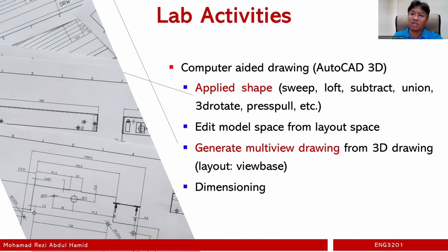And of course, you're going to create a multi-view drawing, but in this case, you don't do that manually. We're going to use a feature called Viewbase, and you will need to do this in the layout tab as opposed to in the model space. And of course, once you have created your drawing, just do dimensioning as usual.